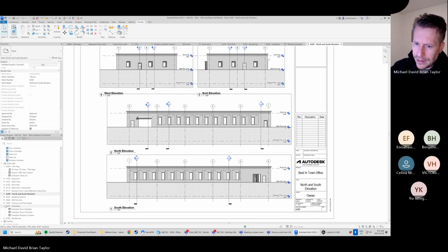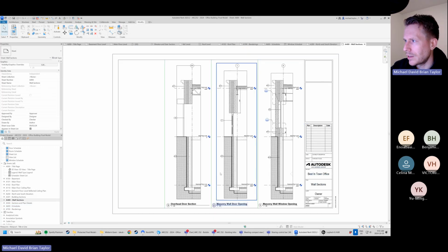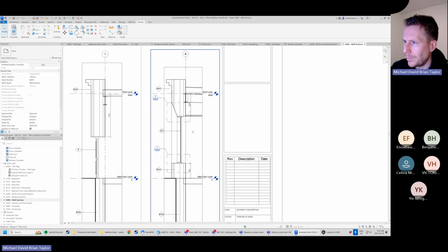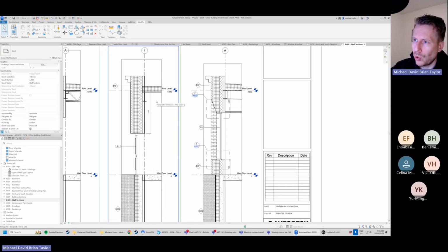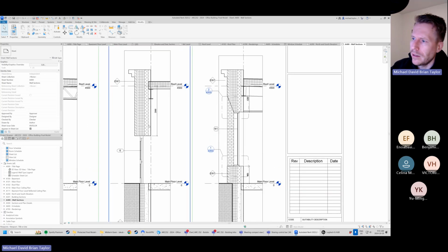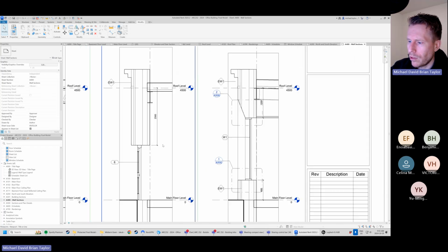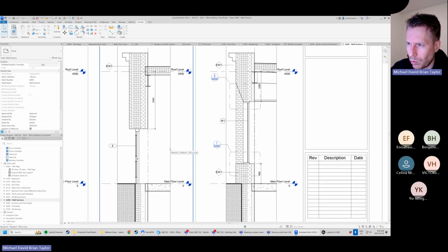Last, at least I think it's going to be the last thing. The last thing is for the wall sections. If you missed this step, there was one thing with our level of detail in our drawing. So what I wanted to make sure that we know how to do is set up our drawings to show the insulation, the kind of depth of all of the systems here, rather than show it as what's called a poche or a solid color for these systems.